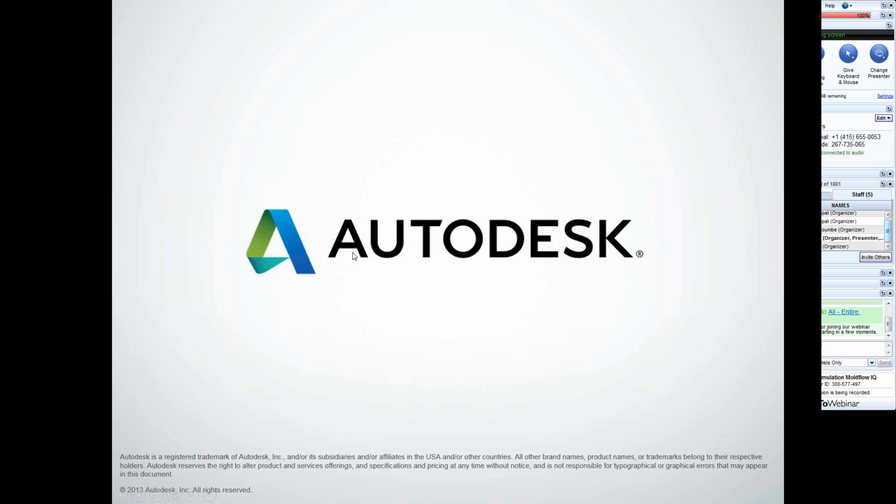I actually just got another one here. Can I mix 3D, dual domain, and mid-plane? Yeah, you can. Again, it's going to have to be a 3D part model with a dual domain or mid-plane runner system. But yes, you can mix those together.